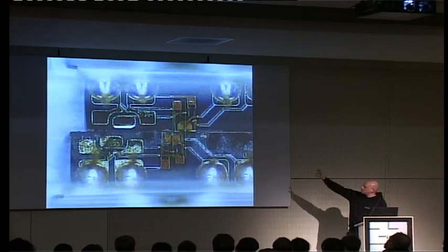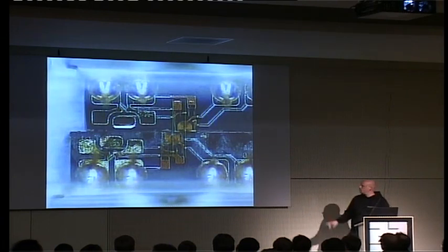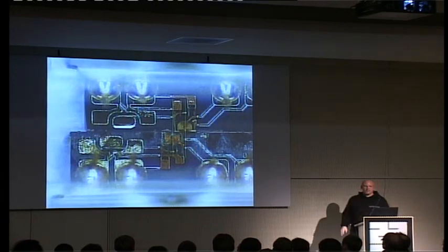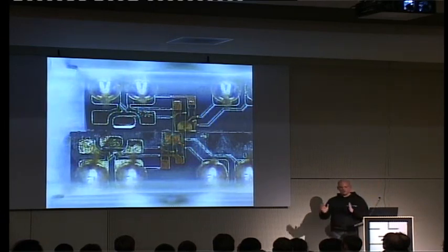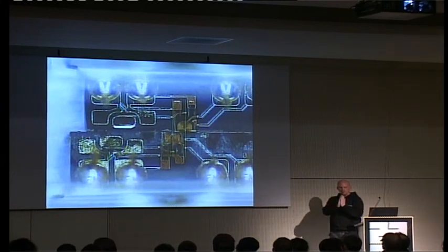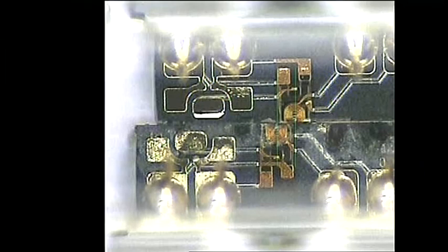It's two heads together. You can see those traces, those electric connections, and you can see at least 4 electric connections. Actually, the read and the write element are not one, it's 2 elements. First you've got the MR element to read, and on top of that you usually have a thin film coil that actually writes the data, that writes the transition to the media.